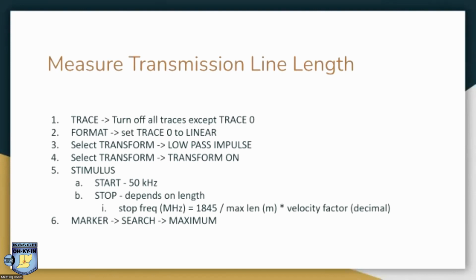How long is your cable? This one I believe was 25 feet. Your length is in meters in your formula. 25 feet is not 100 meters. He's got his max set for 100 meters, that's about 330 feet.